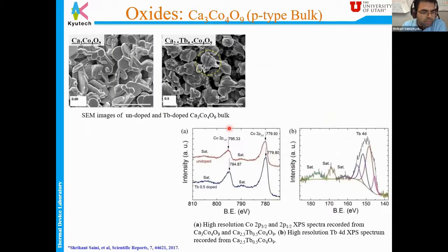And then we see the SEM image, what is happening here. When we take the pure material, the pure material shows a flake kind of structure, a grain of flake kind. But when you dope it, you get interdiffused grains, and the grain size is also increased, and it becomes like a chunk, you can call it. Two or three flakes are connecting together, and it is interdiffused very well and quite melted in all the scenarios if you see this kind of SEM.